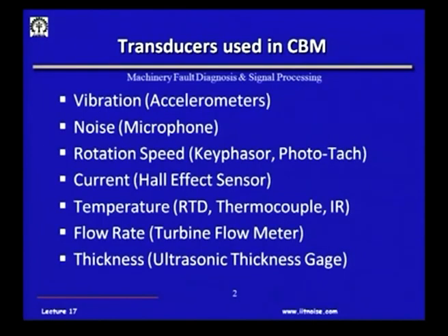And then next comes temperature. I do not mean temperature of a human being here, but temperature of machineries, temperature of bearings, temperature of oil baths in the gearboxes, and these temperatures could be very high. Imagine the temperature of a blast furnace. Inside a blast furnace, I possibly cannot stick in a thermometer. So, we have to use certain non-contacting type sensors like infrared sensors or pyrometers, and for a high range of temperature, perhaps the thermocouples or the RTDs, resistance temperature detectors.